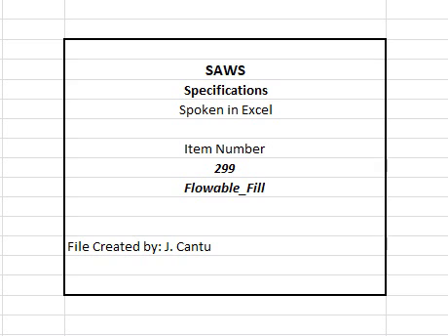1. Mix design number or code designation to order the concrete from the supplier. 2. Design strength at 7 days, unless otherwise noted on the plans. 3. Cement type and brand. 4. Fly ash type and brand. 5. Admixtures type and brand. 6. Proportions of each material used. 7. Submit a copy of delivery tickets accompanied by batch tickets, providing the information required by ASTM C94 to SAWS inspector in the field at time of delivery.